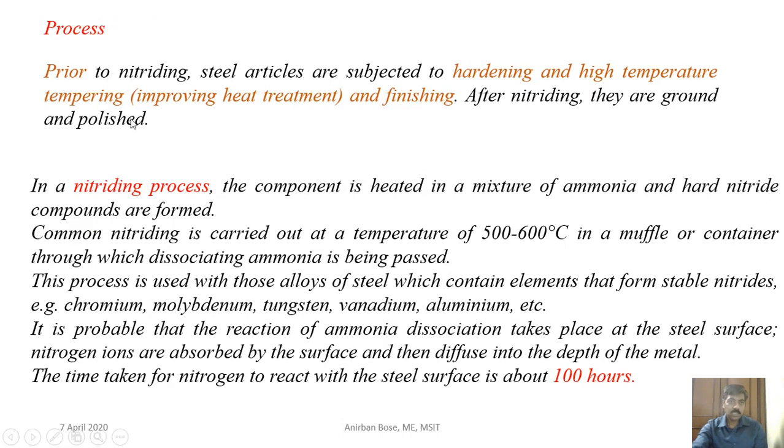Now, in the process, remember one thing: before the nitriding process, you have to do all the heat treatment, because after nitriding there is no requirement of quenching and all that. So all the heat treatment process is to be done before nitriding, and after nitriding, it is basically the surface finishing operation that is done.